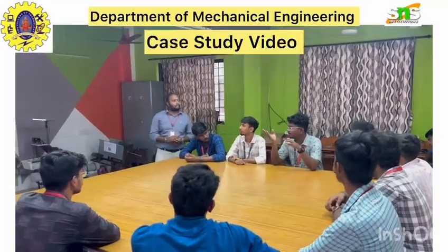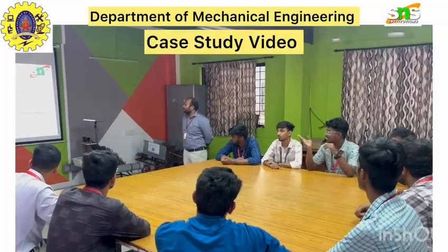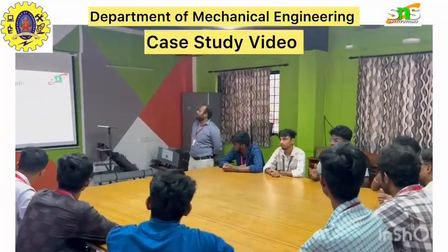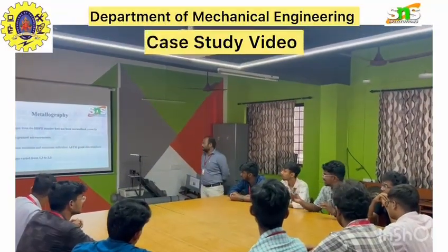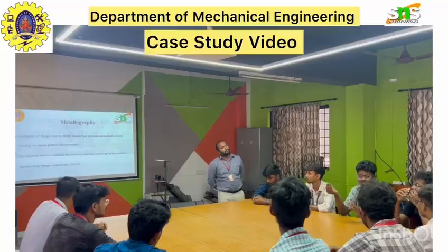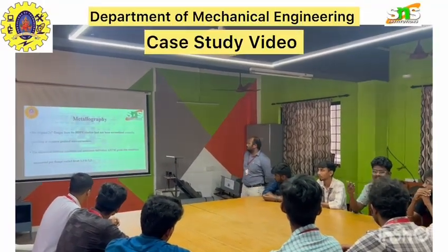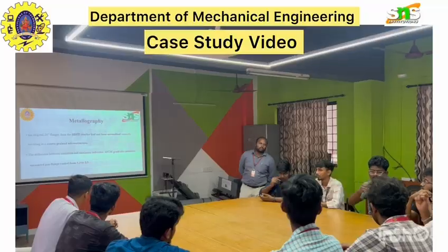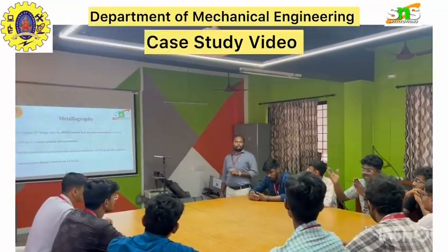Here, the 24 inch flanges for the high density polyethylene reactor have not been normalized, so a coarse grain microstructure has occurred. The difference between the minimum and maximum individual ASTM grain size measured per flange is from 1.3 to 2.3, as mentioned by ASTM.